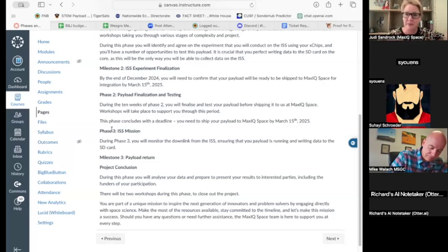So really make sure that it's not good enough that it's just writing data to the SD card. Make sure that you can power cycle it multiple times and that it actually creates a new file each time. So that is really something for you to look out for.